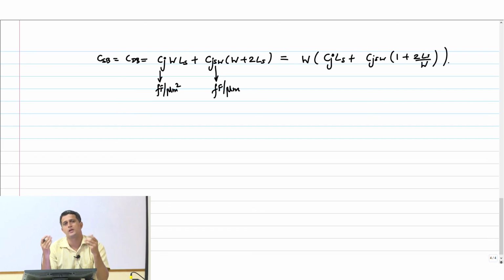So if you tell me that I will just make the size of the transistor much bigger, then be aware that you are going to actually load the previous guy significantly more. On the other hand, if you increase W, like we discussed in last class, the resistance drops. R equivalent is proportional to 1 over W. The resistance drops, there is no doubt about it.